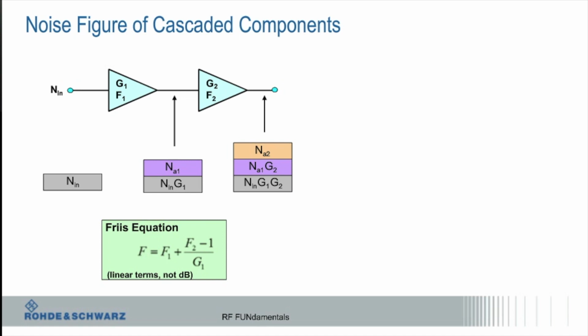So one of the questions is, when I look at a chain of amplifiers, say I had a 10 dB amplifier followed by another, so G1 is 10, G2 is 10, the overall gain of those two amplifiers is 10 plus 10, right, in dBs. So that's easy, but what is the noise figure? The noise figures don't just add. The interesting thing is they're really a function of the gain in front of the stage preceding that device.